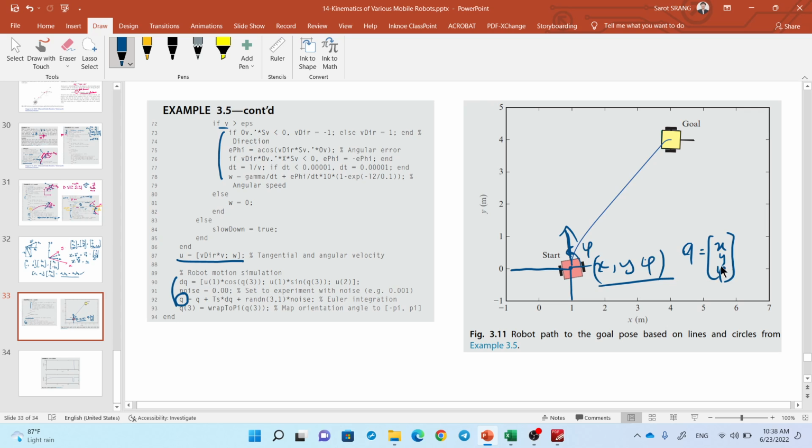From this, for phi you can construct the orientation or rotation matrix. For x and y you can construct the origin of the robot. So with this information, you can plot the robot at a certain location. In order to simulate this, it's better to have code to draw the robot body, plotted according to the location of the center and the orientation described by the rotation matrix. So you can test this algorithm and see an animation of the robot motion.